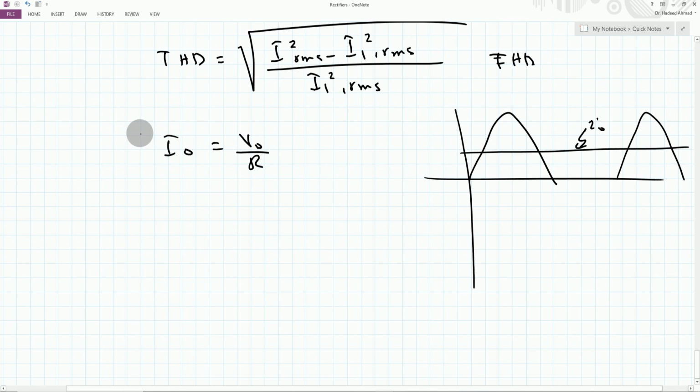So if I look at this particular circuit, if I want to create this type of waveform, I do know that the average load current is controlled by the resistance. However, the inductance has its impact on the load current with the AC quantities, and therefore to get rid of the AC component present in the output load current, we can make XL equal to infinity, and that means this inductance should be high enough that this current becomes equal to a constant value.